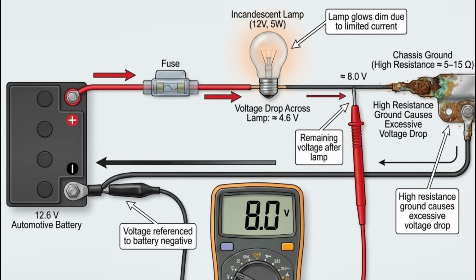That's why on cars with bad earths, old Renaults, Citroens, anything with tired wiring, you press the brake pedal and the side lights glow, or the fog light comes on dim. The brake light hasn't magically powered them, it's borrowed their ground. The circuit is still complete, just in completely the wrong way. Once that ground opens fully, everything stops. But until then, electricity will always find some way home.